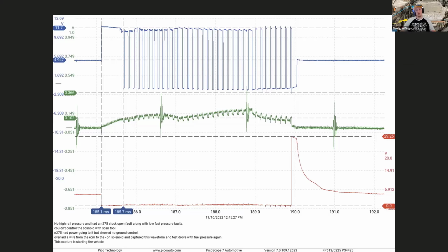So what I'd really like to do is get a hold of one, get a high pressure pump off of it, dig into it, take it apart, look at it, and see how it's constructed to see if it's different. But the other fascinating thing is the published information talking about the solenoid resistance for the high pressure pump actually lists the solenoid resistance the same for the generation 3 and the generation 3B, which can't be correct because based on current flow, that's not possible. Solenoid resistance cannot be identical. That's not going to work from an Ohm's law perspective, right?